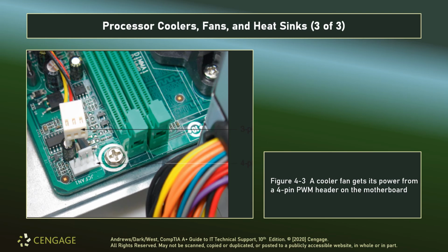I have seen some that are 2 connectors in one. They're each going to be 2 pins, which is literally just a positive and a negative lead. And then that will allow you to connect 2 fans to the same connector. I've also seen some that are very extensive, like a PCI X1 slot, and it will have several pin connectors on the edges, which will then allow you to connect several fans at once. As I said, my machine can easily hold 7, possibly 8 fans. I think there's actually a fan that's on the side of the drive bay as well to help keep that cool.